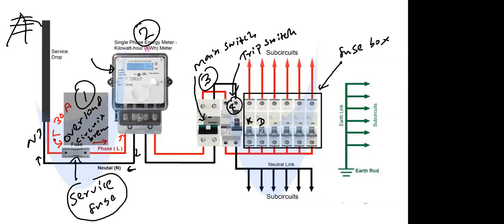Each fuse has an ampere value. So imagine this is 6 ampere value. So imagine this is 10 ampere value. If you are exceeding that ampere value, then this will go off. Imagine the kitchen, all the plug points and everything, only 6 amperes. Now you connect so many plug points and try to get more than 6 amperes. Then this will not allow that. Understood? So that is why it controls the amount of current that flows to each branch. That is also for the safety.